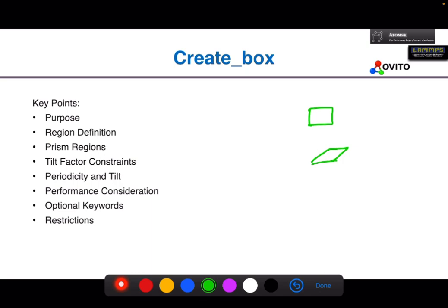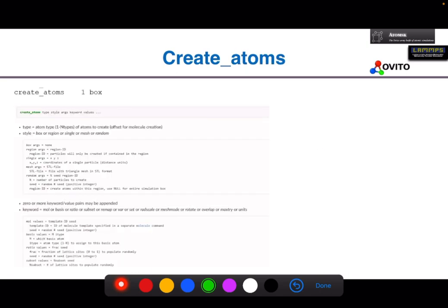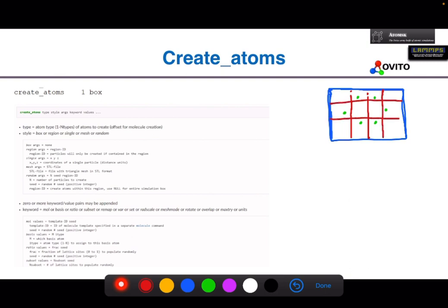Okay, so the main restriction is you need to define the atom style and region before creation of the atoms. So finally we have reached the creation of the atoms. Up until this point, we have created the lattice which determines the positions where the atoms would be generated. Then we have created a block saying that this is the region where our unit cell would be. Next we have used create box, which effectively helps us in dividing this block into subdomains for simulations.